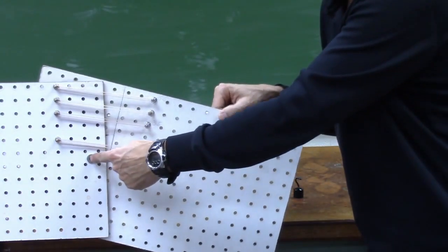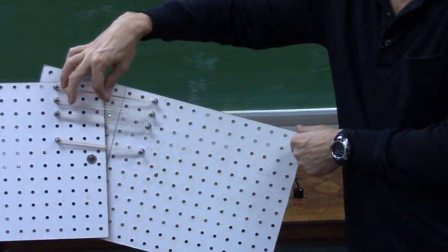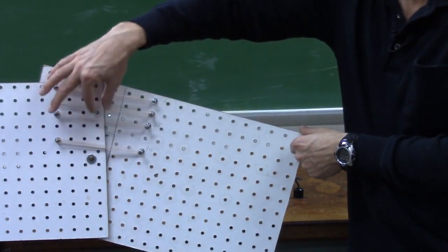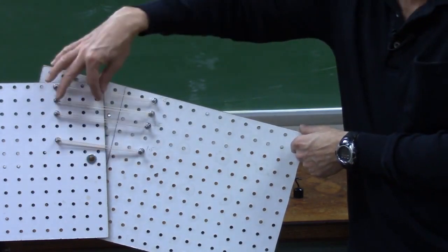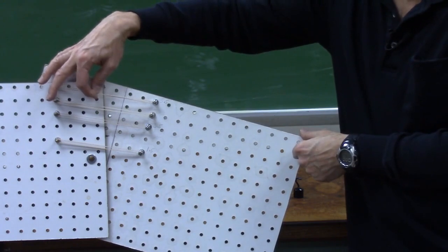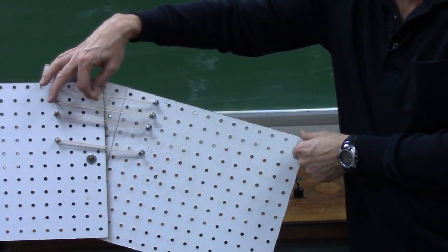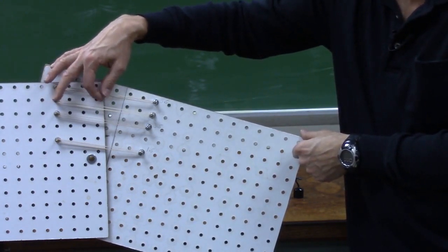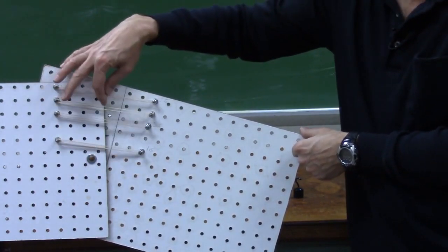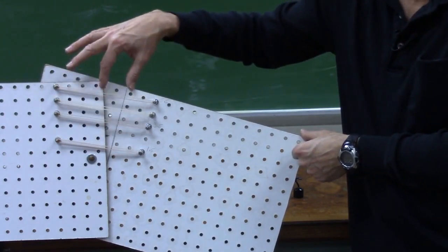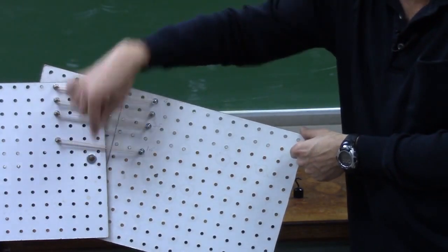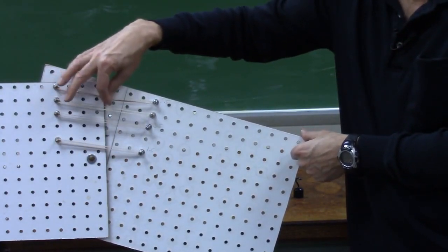Then, using this point along the neutral surface as a pivot, you can see that the corresponding torque is proportional to this force times the distance above the neutral surface, since the distance up from the neutral surface is perpendicular to the direction of this force. So the lever arm equals the distance above the neutral surface. So the force in each fiber, the tension in each fiber, is proportional to how far up that fiber is from the neutral surface, and there's an additional factor of how far up we are from the neutral surface to turn that force into a torque. So that's 2 factors of y, this distance above the neutral surface. One for how stretched things are, this geometrical triangle shape, and a second for the lever arm to turn this force into a torque. So the contribution to the torque about this pivot from a fiber a distance y above the neutral surface is proportional to y squared.